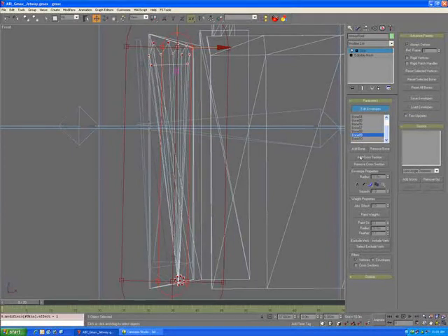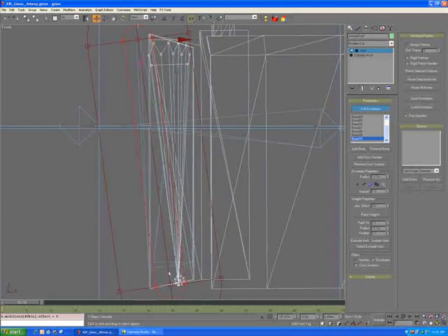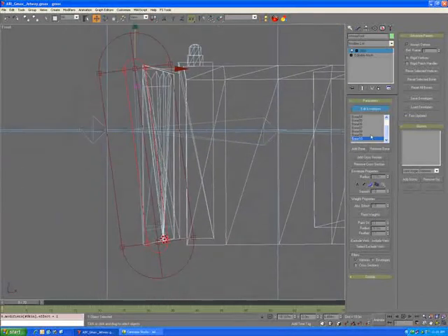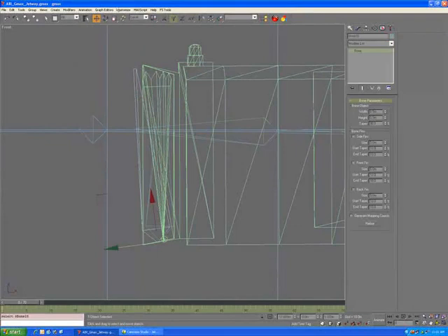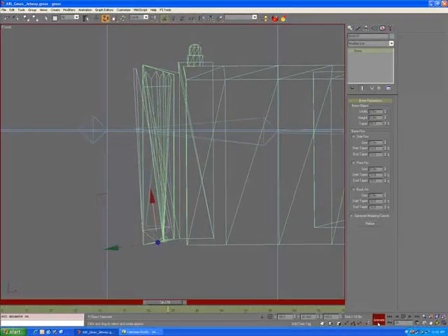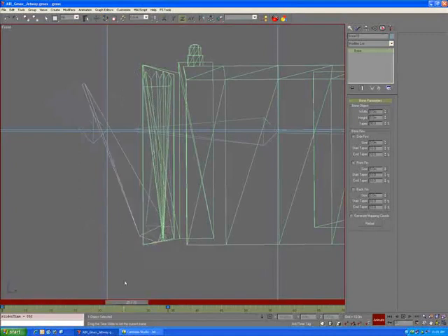And then what we will do is we'll add envelopes in for bone 10. We're going to turn off the edit envelopes real quick. So what we're going to do is animate bone 10 here, just like it would be an extension. So we'll go out to this keyframe, turn on animate. Basically we'll extend it to about the position we want it to extend to there.